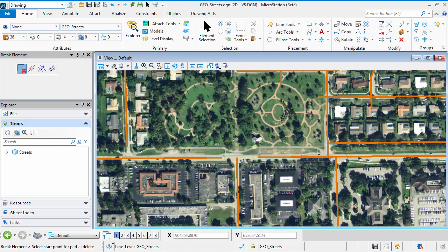Now I can actually come back and do my trim to intersection. Select this one here and that one there to create that intersection if I wanted to do it again. I can do it with that side as well. So using the trim tools and the modification tools makes life a lot easier. Whenever you've got these things out there, you simply select the side you want to keep, go to the cutting element. It becomes pretty easy once you get the hang of it.